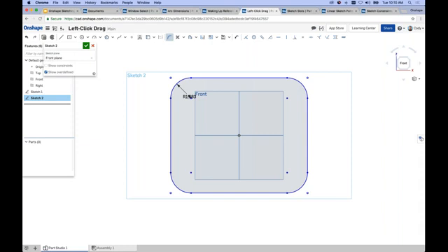So just to reiterate this comment, left clicking keeps adding new lines, but it stops adding new lines when you click on an existing vertex. And that is by design. If it's something you don't care for, please let us know. But the idea behind that is that once you've selected another vertex from that existing entity, the assumption is you wouldn't want to go further, right?